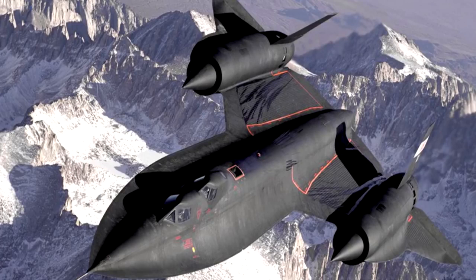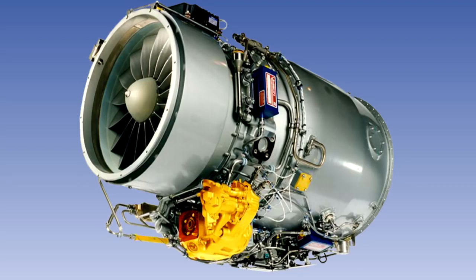The SR-71 Blackbird was the first aircraft to make extensive use of titanium within its structure, paving the way for its use in modern fighter and commercial aircraft. The Boeing 777 uses some 58 tons of titanium in its construction. Magnesium alloys are also used, their principal advantage being weight. Magnesium alloy has an excellent strength-to-weight ratio, aluminium of the same strength being 1.5 times heavier. Magnesium alloy has poor elastic properties, so its use in primary structures is limited. It is often used in the construction of gearboxes.